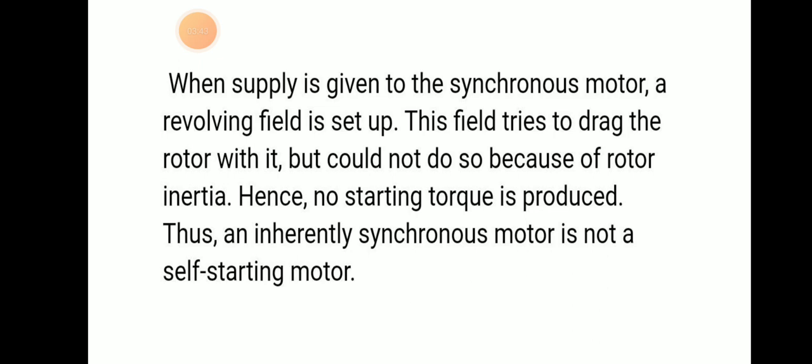But a synchronous motor is not a self-starting motor, because when supply is given to a synchronous motor, a revolving field is set up. This field will try to drag the rotor with it, but could not do so because of rotor inertia. So no starting torque is produced in it. So it cannot start by itself. This is not a self-starting motor.